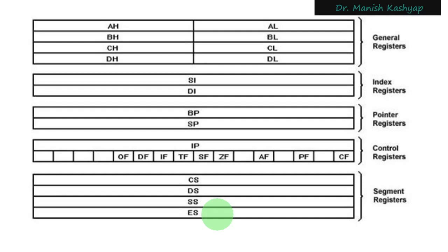And inside the microprocessor, to hold the starting address of that, we have got these 16-bit segment registers: code segment, data segment, stack segment, and extra segment. So this is not the code segment itself. This is a register which keeps the first 16 bits of the 20-bit address of the code segment, because the least significant 4 bits are by default 0. This is a restriction in 8086 that wherever you start your segment from, it has to begin in that way. So these segment registers are used for that particular purpose.